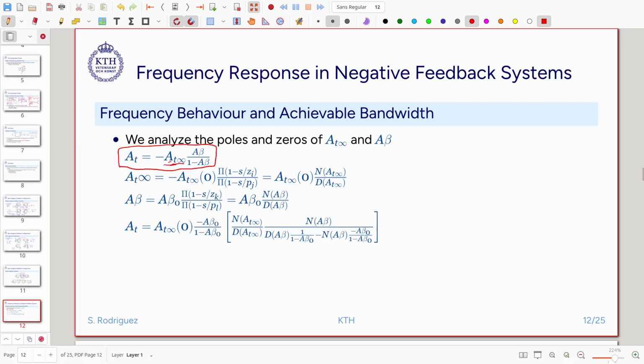So we have the first term, the asymptotic gain, assuming that the amplifier is ideal. It can be represented with a DC level, and then the DC level is going to be 0, because it is a 0 Hertz, so we take this 0 Hertz. And then there will be a number of zeros and a number of poles. Okay, so we will have this transfer function. So we will call this product of zeros and product of poles N asymptotic gain and D asymptotic gain. So this will be all the product of the zeros, and this will be all the product of the poles.